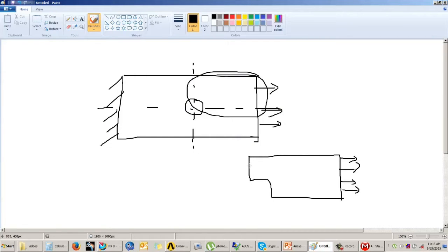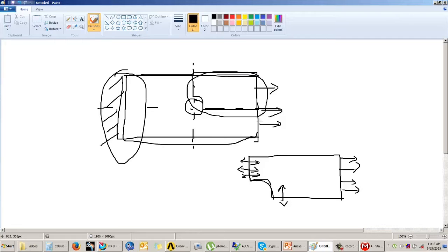But where will you fix the model, because this area is not there in the model now? Whenever you create a symmetrical model, you need to apply some constraints over here and over here. Why? Because practically, even if you have created a 1/4 section, this area has to be considered.